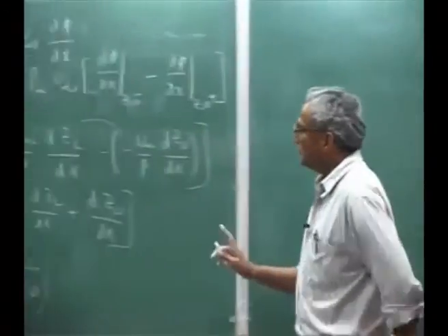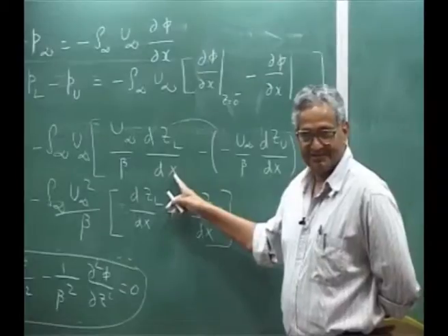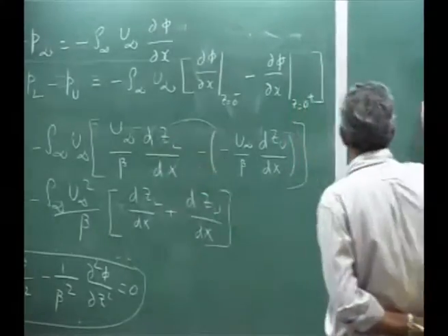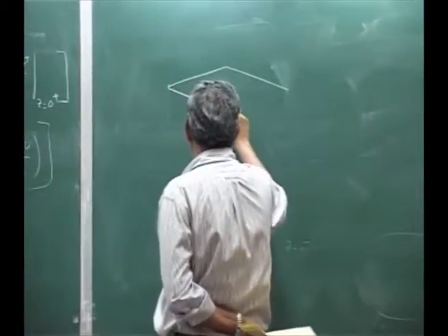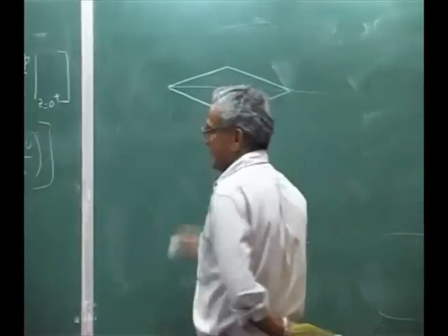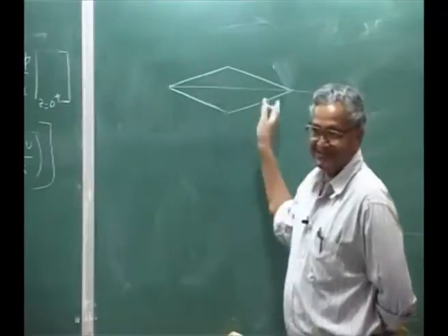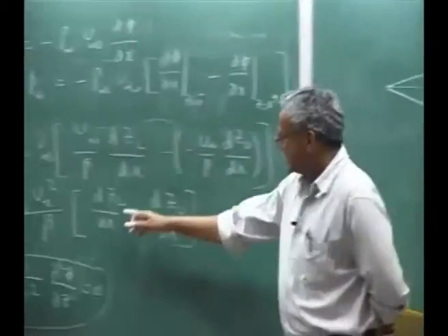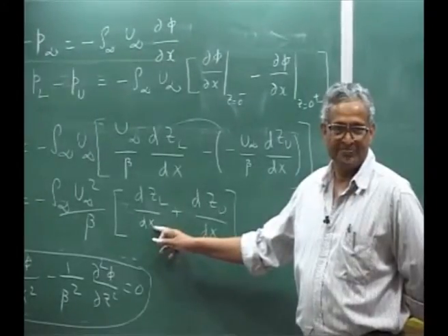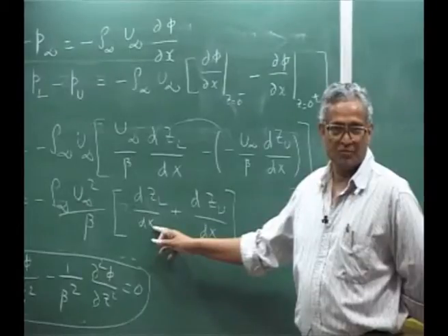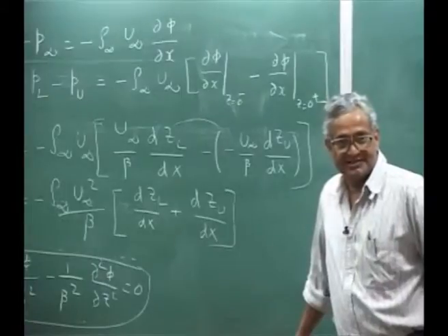Now please understand, this is what it is. If you know the top surface equation, suppose if your aerofoil is like this. Why it is a supersonic flow, supersonic aerofoils are this type of straight line is because they are just related to the slope. The local slope on the surface determines what is the pressure on the surface.